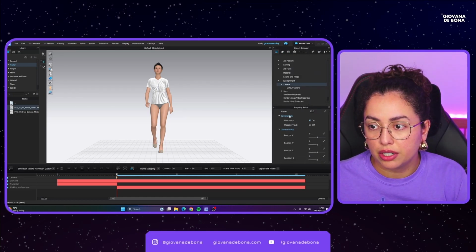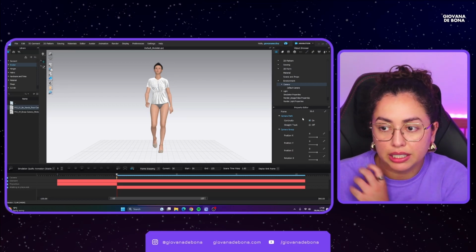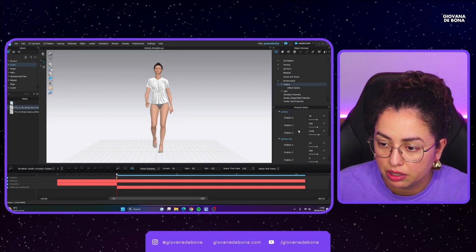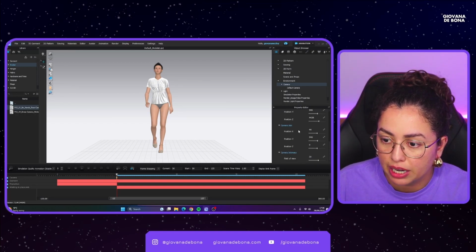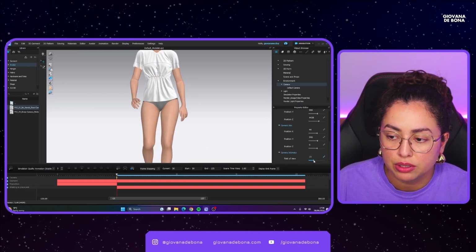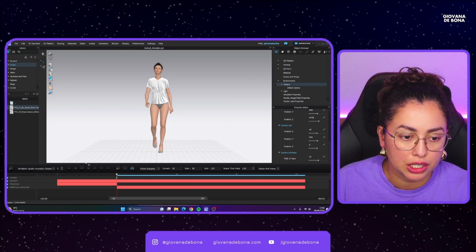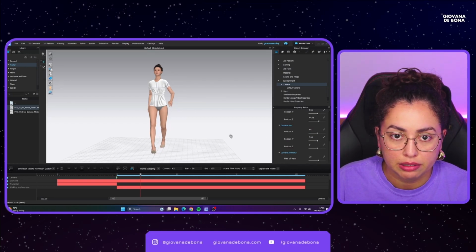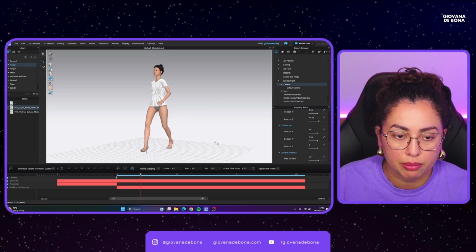You can see here you have a few different settings now with the camera path, camera group, camera position. So this is my current position, camera aim, field of view as well. So literally you would maybe play your animation a little bit, and then let's say I just rotate my camera and I add another keyframe.